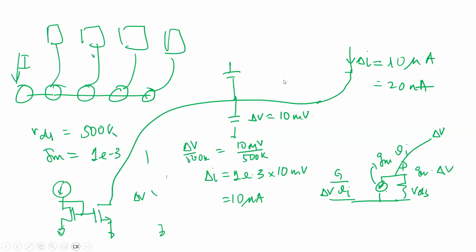Okay, so is that clear why we ship currents instead of voltages now? Because the voltage gets multiplied by GM, which usually you want to be a higher number. So it gets multiplied and your current will be amplified if it is a noise signal, right? If you're sending it as a drain, then that same voltage will get divided by the R out, which you want to be a higher number. So that means that noise current now will be much smaller. Okay? Make sense?